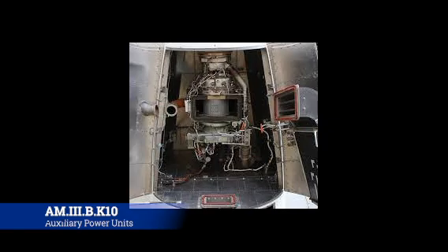The APU is really just for ground handling, and it also has the added benefit of being able to be a backup power source. So if, like, say you're flying along and boom, you lose both engines for whatever reason, you can always turn the APU on, and that gives you enough power to work the radios, gives you hydraulic power to fly the airplane to where it's going, all that kind of stuff. And so the APU is nested, and we've talked about it before, into the power distribution network of the aircraft. But it also has just a redundancy effect for pretty much all systems, because it's effectively just a third engine back there that just doesn't provide thrust.